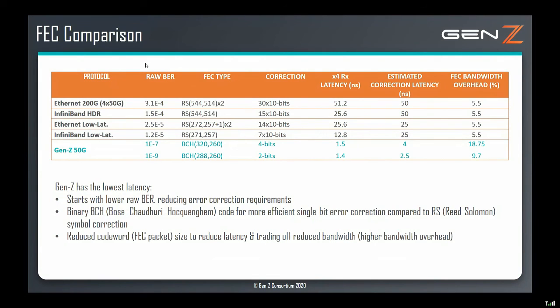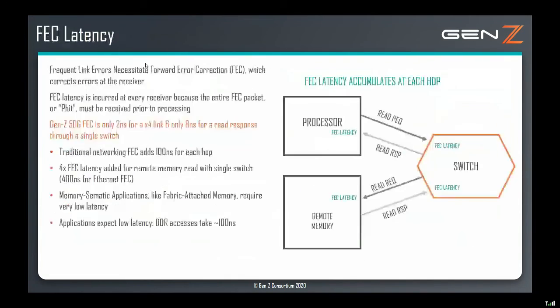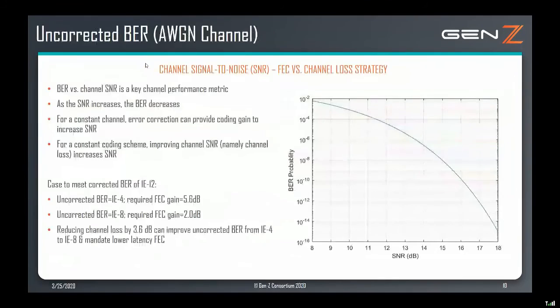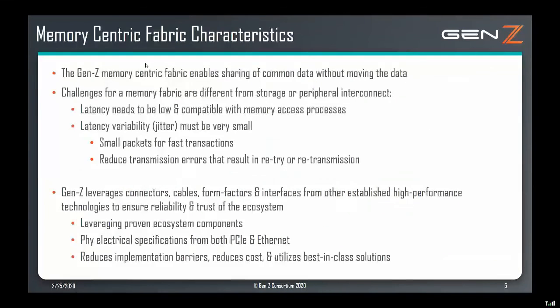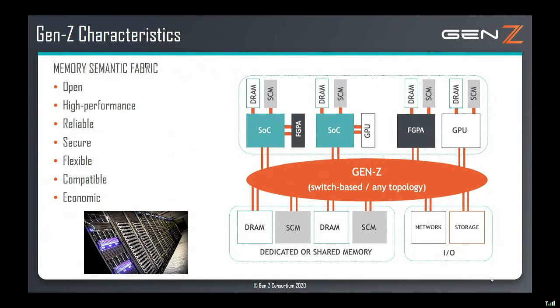And yes, the straightforward answer is yes. It's not as trivial as just allowing both servers to access one piece of memory. You really want to be coherent if they're literally sharing the same space, so that one server doesn't overwrite the same data in the same memory space. So normally it's partitioned, and so although they're sharing one physical device's memory, you'd share an area within that memory. However, it is possible, and it is an objective that 2 processors could share the same memory space.